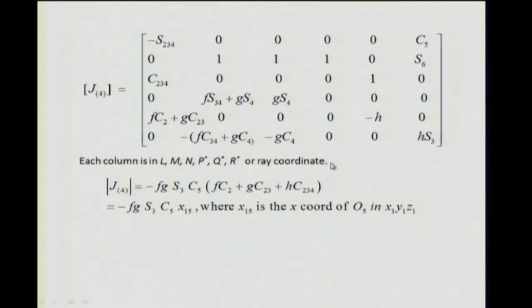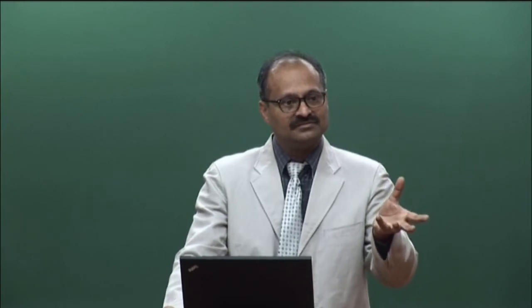in the next lecture. I want to do this slowly. So what are the things we now have to do? I have a Jacobian which is sitting on the 4th coordinate system, right? I can invert in the 4th coordinate system, I can do all kinds of things. So I can find joint rates in the fourth coordinate system. But to really use this, I must then bring everything which I have, all my targets.